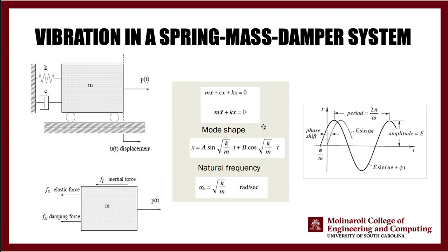Okay. We don't really have a closed form solution for this problem if you do not have the appropriate boundary conditions. Mode shapes in general are going to look like this, and we do have a natural frequency that we can calculate for any vibrating system. In this lab, we are interested in the mode shapes, essentially how the vibration happens, and we are also interested in these points. As you can see, this is going to be your amplitude, essentially how high your beam is vibrating.